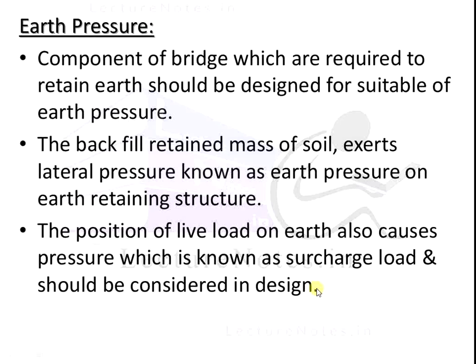The position of the live load on the earth also causes pressure coming on the bridge. It is also known as the surcharge load, and it should be considered at the time of the design of the bridge.